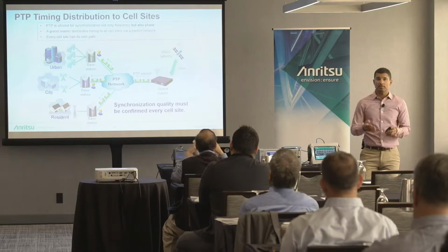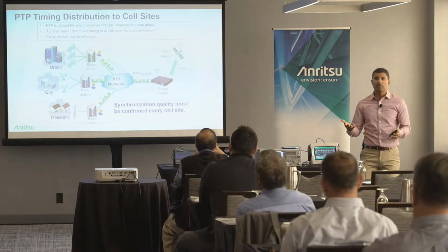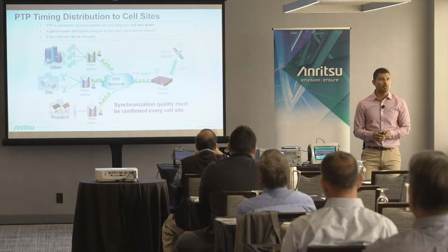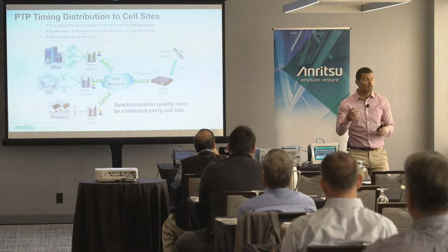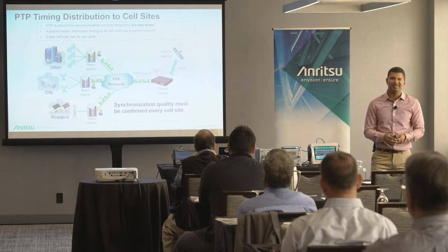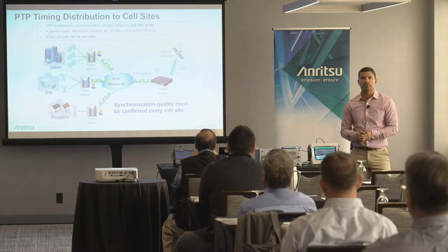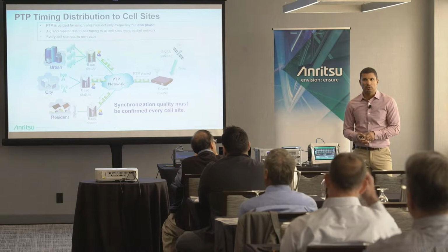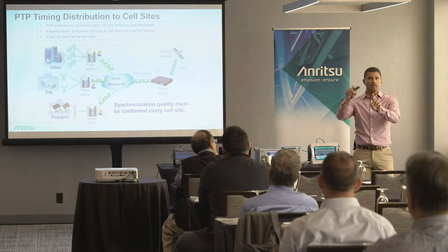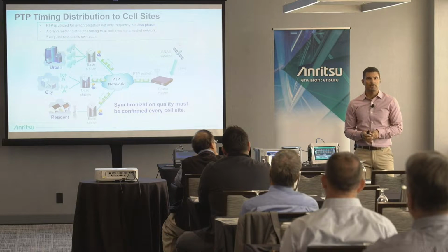Why is that important? Because compared to 4G, what happens when you lose your timing in 4G? You switch over to holdover timing, right? Your site would go to holdover, and it could maintain holdover well, depending on the type of clock source built into it. It wasn't as detrimental as it is for 5G, because in 5G, once you switch over to holdover, if that holdover isn't synchronized to the neighboring stations, do you have coordinated multipoint? No, you don't. You don't have TDD, and then you're in trouble.